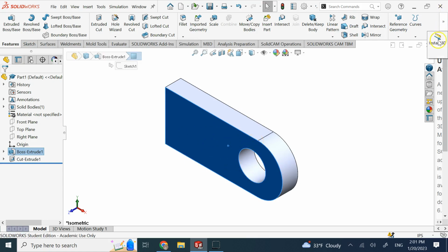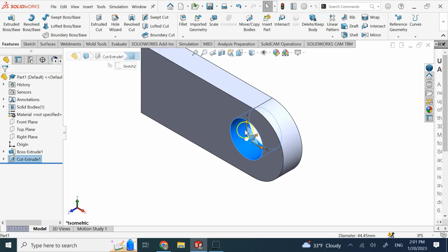But if I go ahead and activate this option, right? So now it's active. Look. Now what's going to happen? If I click on this hole, now it gives me these axes. And look what happens when I grab these axes and move. You see, I can easily relocate the hole in the X direction, in the Y direction, right? And there is this guy here that allows me to resize the diameter. So there are 3 axes for location, X, Y, and for the diameter.